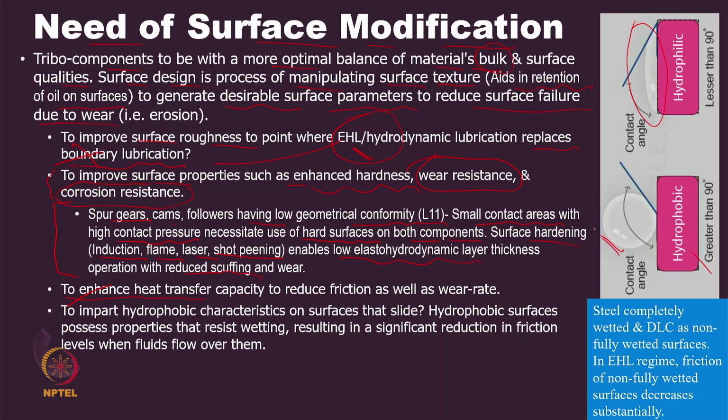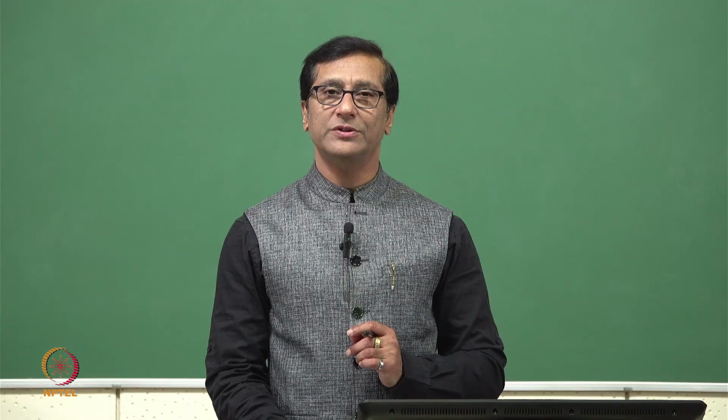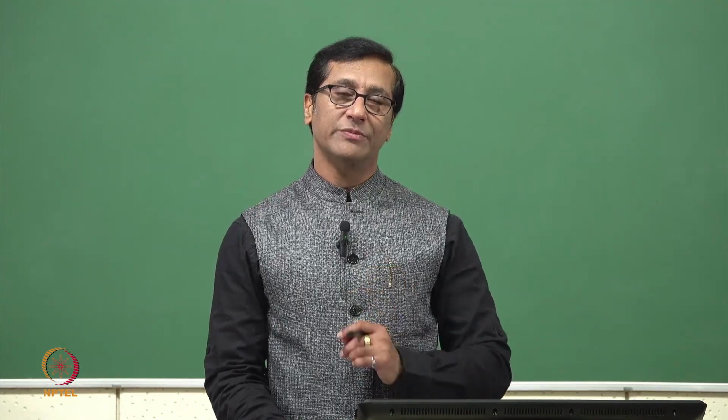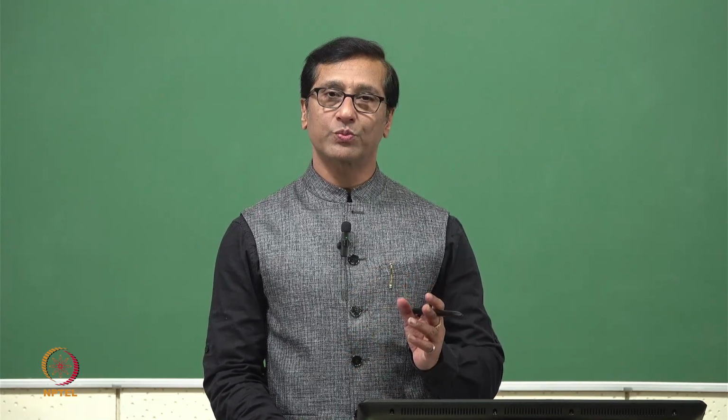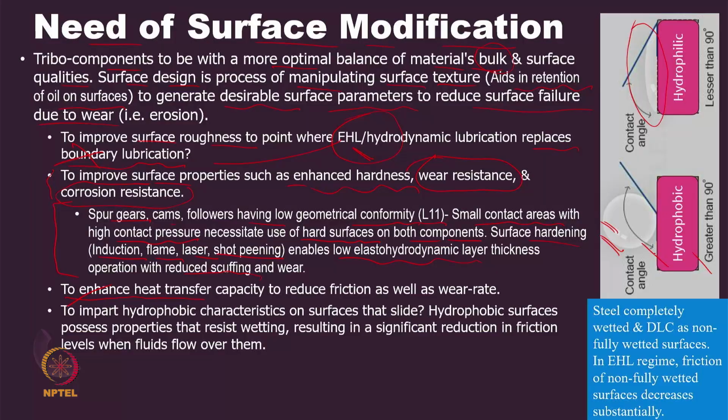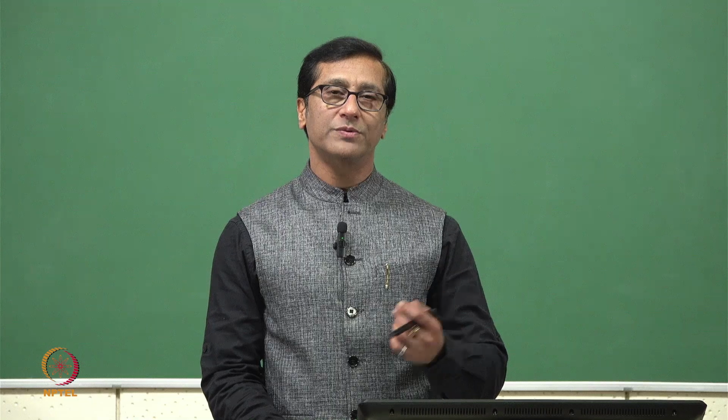While coming to the non-wettability or limited wettability, the molecules of the water will remain on the surface, a drop of the water will remain on the surface, it will not spread. In this situation, the coefficient of friction will be lower in case of a hydrophobic surface. Now coming to the oil, if the surface is not getting wetted, or a drop of the oil remains on the surface for a longer time, naturally the availability of that lubricant will reduce the coefficient of friction.